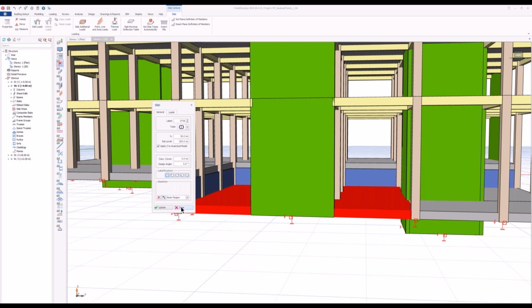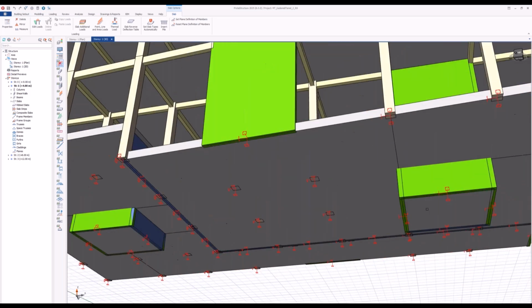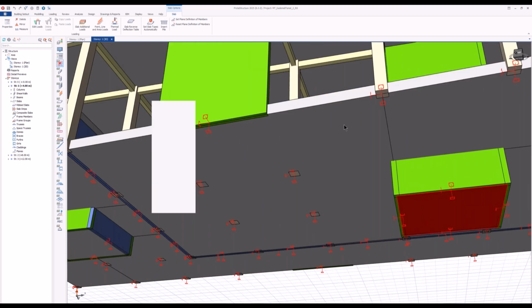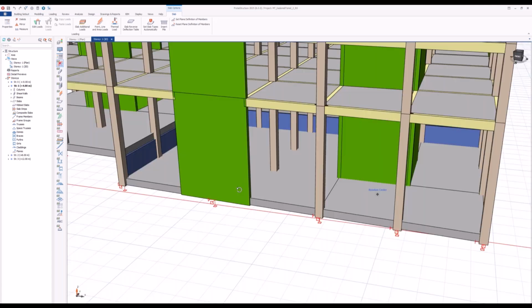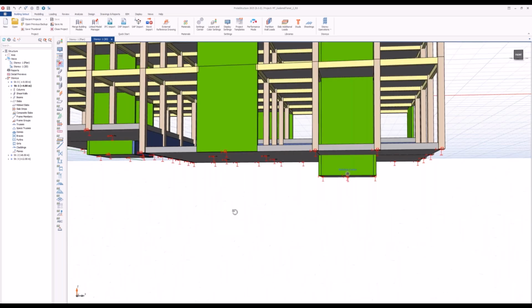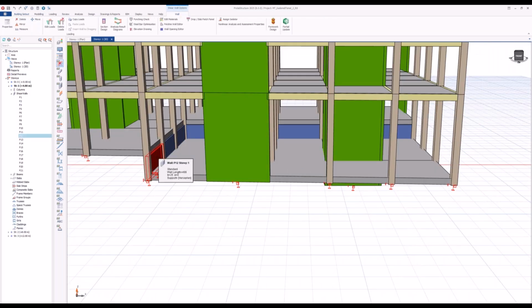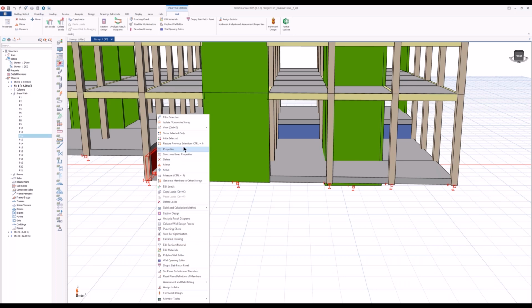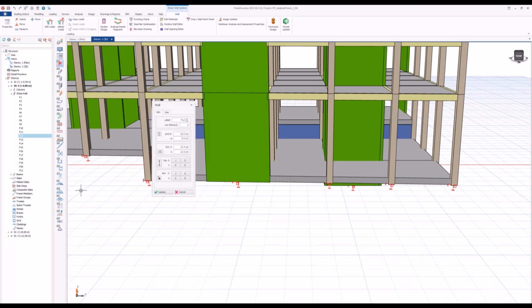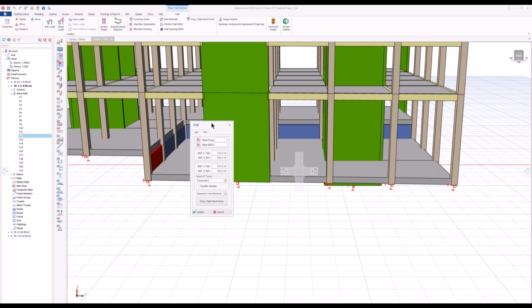Okay, that's very easy. Also, for this slab, maybe we have minus 380, and I want to include them in the analysis model. And you can model, for example, this shear wall here, which is a basement wall defined in Storey 1. When you look at the wall properties, you will see that the top is dropped by 5 meters, and the bottom is dropped by 2 meters.